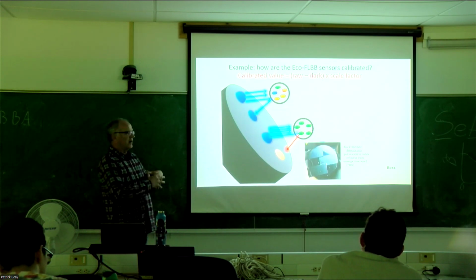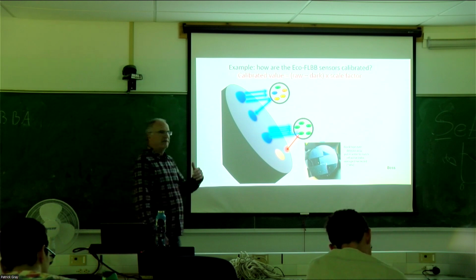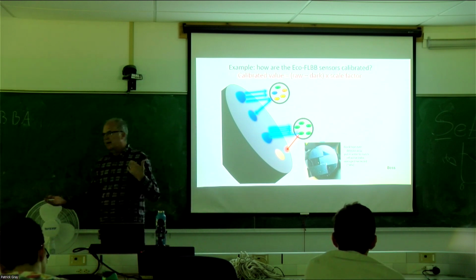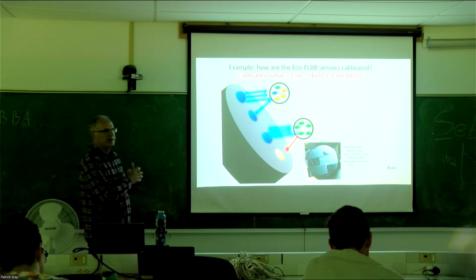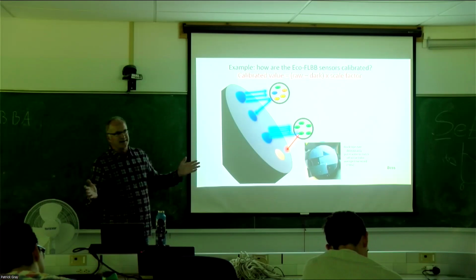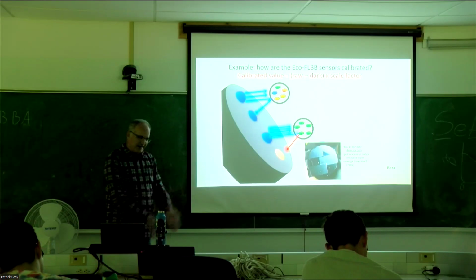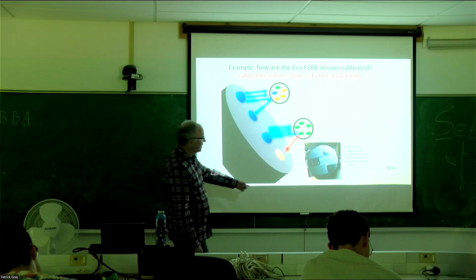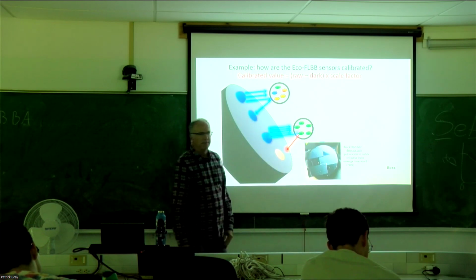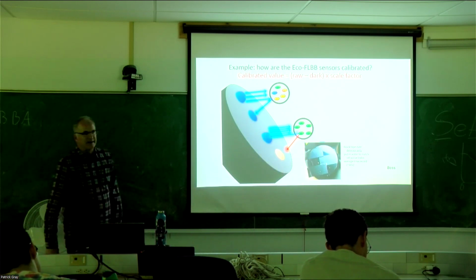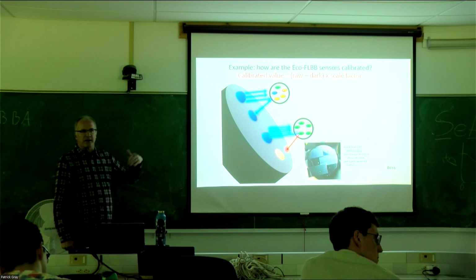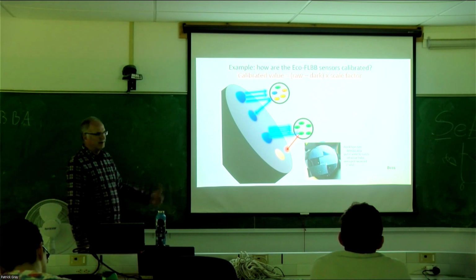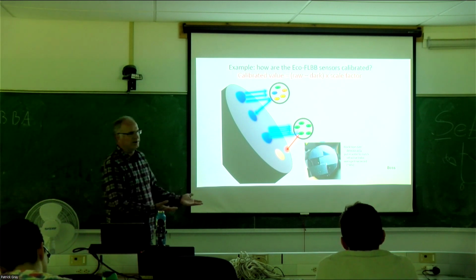So the first thing you do to try to calibrate your instrument is always have to have a dark signal. So this is sort of your blank, if you think about it. What is my signal response when there's no light going out of the instrument and then hitting the detector? So the easiest way to do that, take some black electrical tape over the detector, and then you can measure what the dark counts are. That's why they're called dark counts. There's no light actually hitting the photodiode behind it.